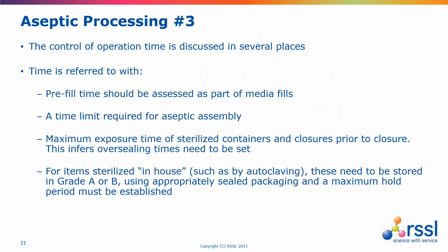Other revisions to the annex which impact on operations conducted within the clean room are kind of around controlling the elements of time, and time features quite often in the annex, and by controlling time, then an overall level of control is introduced. So this could be the time to set up a filling machine should be known. There should be a typical time and perhaps a maximum time, and that should form also part of the media fill.